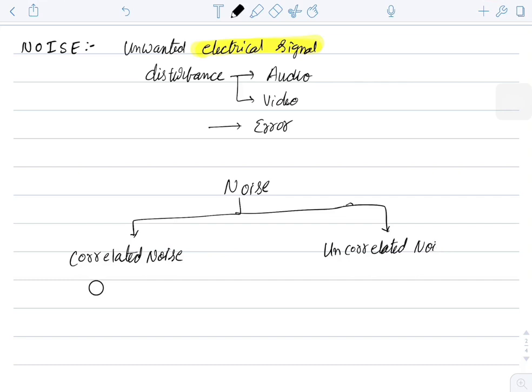That means when the signal is present and you observe any noise there, your input signal for your FM receiver is signal as well as noise. And the noise which is developed here has a relation with the signal. That's why we call this type of noise correlated noise. That means in correlated noise, we have both signal strength as well as noise strength.